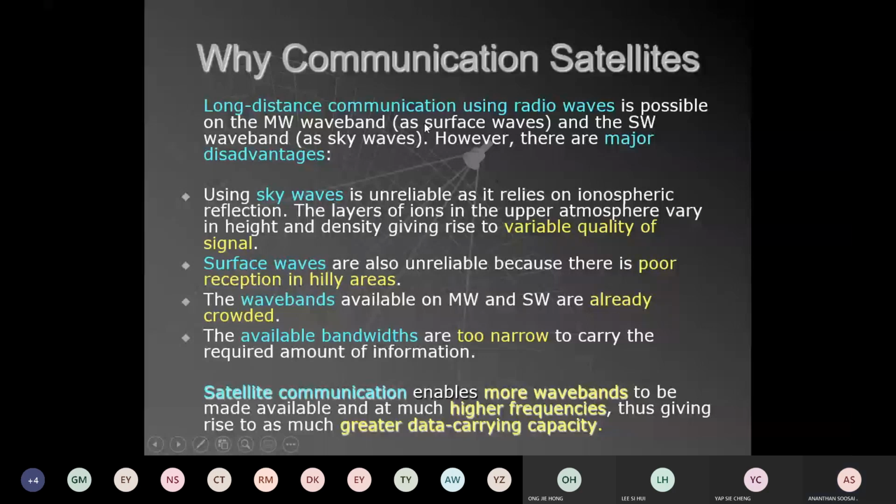It pierces the atmosphere and goes to outer space, so the ionosphere can't reflect it. So high frequency needs a reflector. Who's the reflector? A man-made satellite in outer space. The high frequency signal hits the satellite, and the satellite amplifies the signal and reflects it. That's why satellite communication was needed.